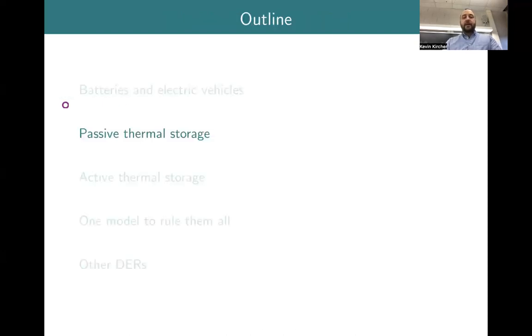All right, simple enough. So we talked about buildings, and we talked about basically the energy storage elements within buildings, essentially the shallow thermal mass that has to do with the air inside of rooms and the first couple of centimeters of walls and things like that. Ducts and other metal that is pretty fast to respond to changes in the air temperature. And then we talked about the deeper thermal mass. If you drilled into this wall, there's a bunch of cinder blocks in here, and if you got a foot deep, the temperature back there would be significantly different than the temperature in the room. More energy storage capacity, but sort of harder to access.